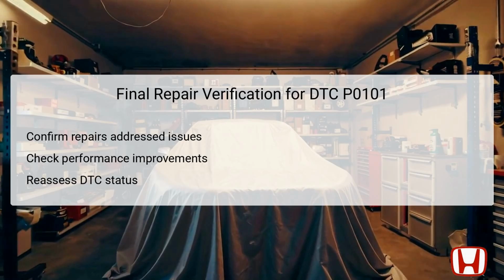Observing how well the engine runs post-repair can indicate whether your interventions have corrected the problem. Check for any remaining DTCs to ensure that all faults have been adequately addressed. It's also wise to monitor for any changes in engine performance, such as improved acceleration and reduced emissions. This step acts as the quality assurance phase of your diagnostic efforts.